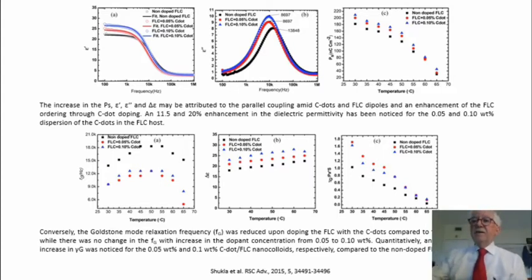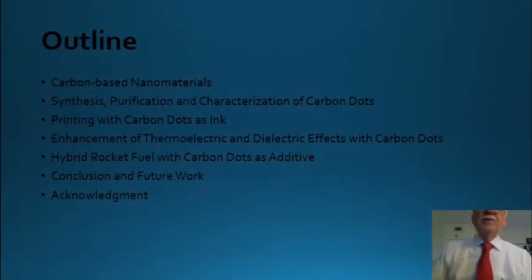So there is a huge effect of introducing the carbon dust into the dielectric system. So a different matrix might be the way to see a different dielectric effect, and this one is only related to one matrix, so it might be interesting to work with different matrices. The overall parameters that we just measured are linked to the fact that carbon dust probably induces what I call a dipole, inducing the ferroelectric liquid crystal dipoles there, because the carbon dust is a system that conducts electricity.